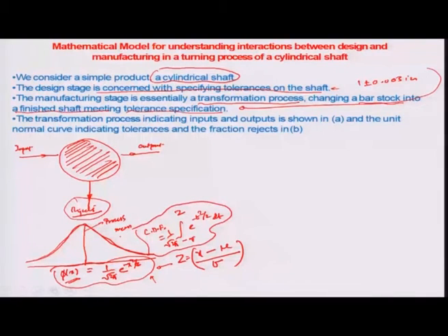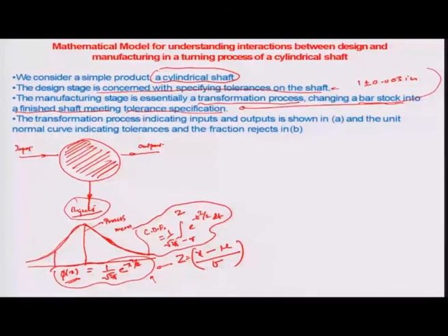So, having said that, and this is all very commonly available information as far as statistical process control goes, I am just going to apply this to the concurrent engineering philosophy that we are talking about when we mention this as an engineering design tool. So, here there are going to be upper specifications and lower specifications given by the design department, which have to be overlapped with this process characterization or process characteristics of a mean and a variance, which is related to a certain process.